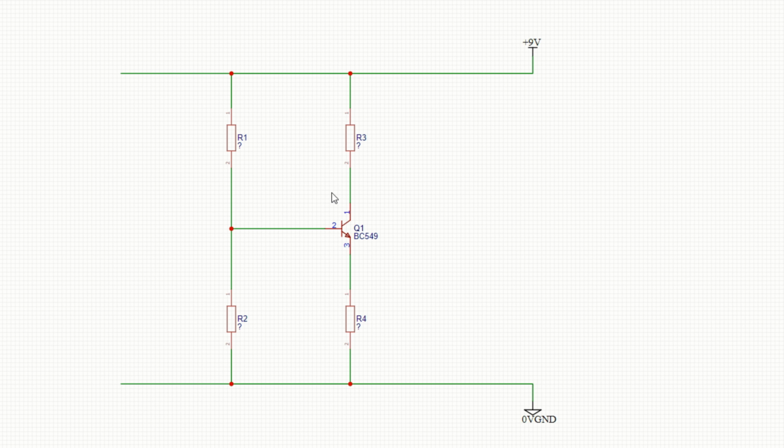This whole setup is specific for small single transistors that have high gain, 100 or more, possibly 300, 500 even. So the base current, which also flows through the emitter, doesn't have a really significant effect on the overall current through the emitter collector chain.